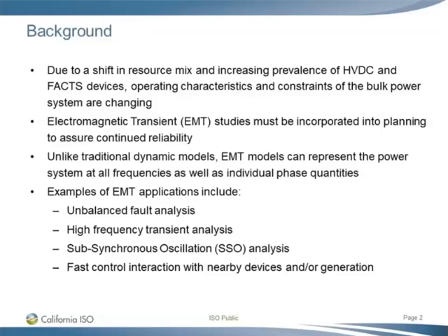EMT models can represent the power system at all frequencies, as well as individual phase quantities. Also, EMT models capture subtransients that happen in a very short time frame. Examples of EMT application include unbalanced fault analysis, high frequency transient analysis, and SSO analysis, subsynchronous oscillation analysis, and, more relevant for inverter-based resources, it can be used to perform fast control interaction studies. Next slide, please.